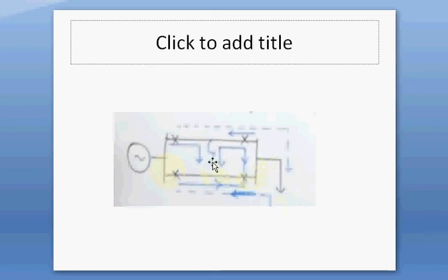Now let us consider there is an occurrence of fault in the upper feeder. Now the current will flow in the upper feeder from generator to relay 1 and it will feed into the fault, and in the lower feeder from generator to relay 3, relay 4 and now it will feed to the fault. Now the direction of current in relay 2 over here is reversed. See this point, the direction initially was from left to right, now the direction is from right to left, so